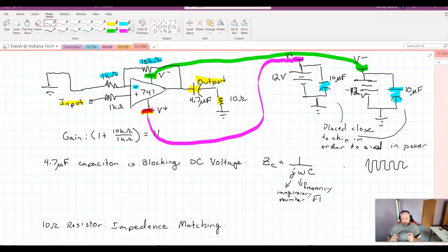So we can store some charge for the op amp to steal away from it, and then it will get recharged by the power supply that might be on the other side of the board, where maybe the battery is located. And so this helps make sure that the chip sees what we call a clean power supply. It helps with preventing noise on the power lines.